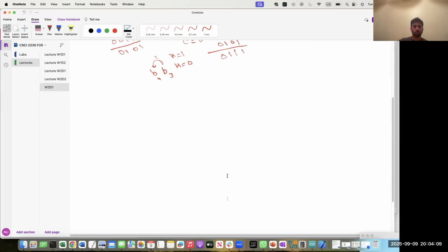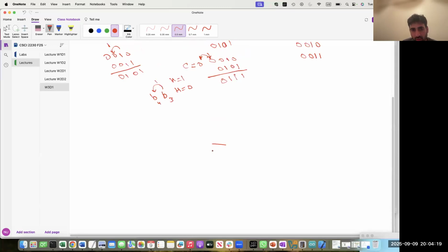Let's say we are writing an assembly program. I'm not writing exact assembly instructions, but let's say we have some instructions here and we have a label here. What we want to do is execute these instructions multiple times, so we want to have a loop. How can we do that? I can say, in register R16, put the value of, let's say I want to do this loop 10 times, put the value of 10. Now in R16, I have 10. And here I have a couple of instructions which I want to execute 10 times.